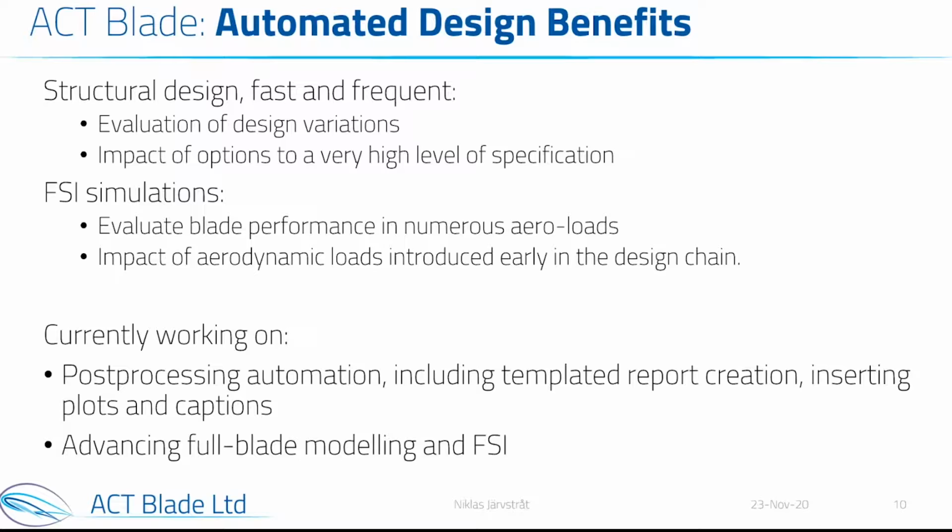If you look at the benefits of automating this design process for us, well, from the structural design perspective, it allows us to do fast and frequent evaluation of design options, and also look at these different options and different variations at a very detailed level. So we can very quickly evaluate different ply layups, different structural options like different core materials in a very automated and structured way.